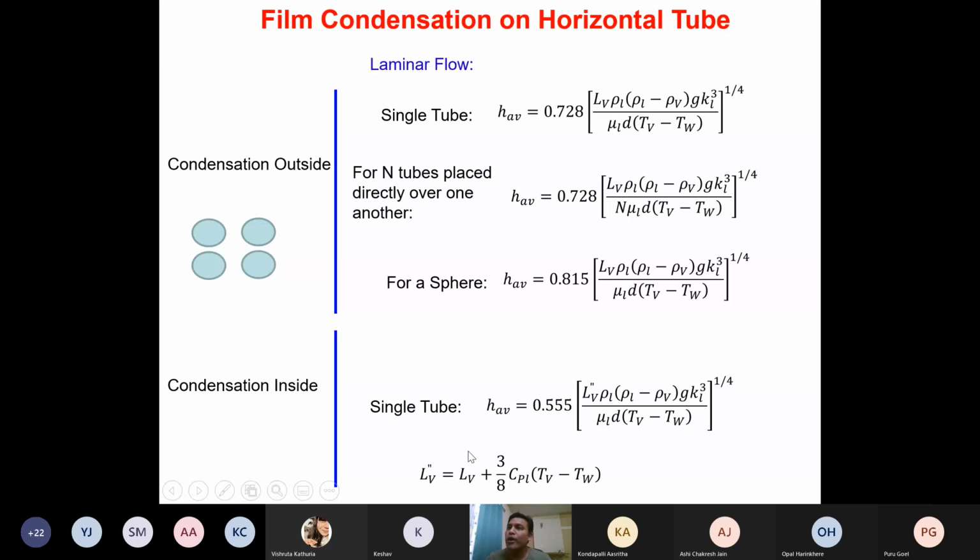Note that when we are looking at condensation inside the tube, we are not assuming that the vapor is saturated, so a degree of superheat is also present. That is why this particular fraction is going to give me the sensible heat, isn't it? And this is just the latent heat. Correct? Is it clear to everyone?